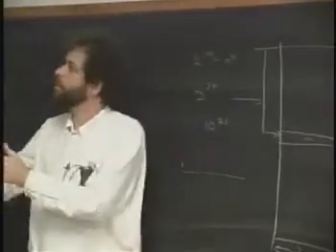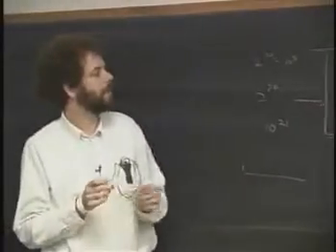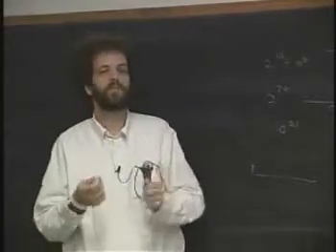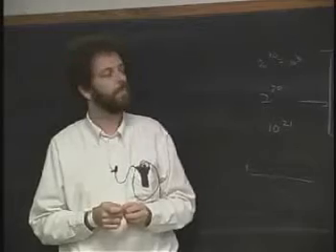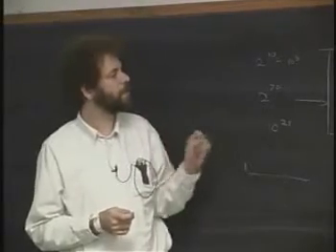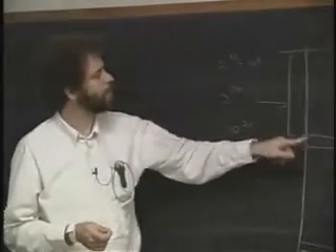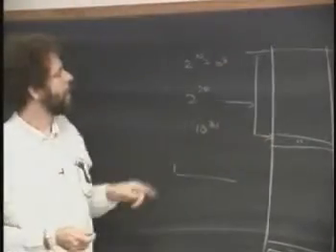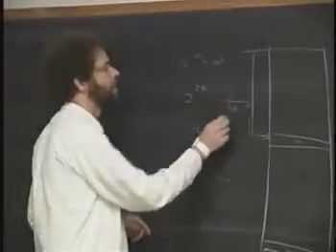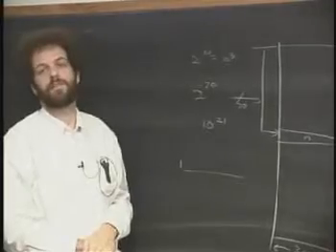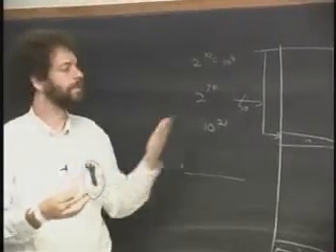So even though we could implement this thing as what's called a lookup table or a memory, notice the architecture here is simply that of a memory, it's impractical to do that, okay? But theoretically, at least, it is what's called a combinatoric logic function, which means that the output is purely a function of whatever the combination is of the 70 bits that go into figuring out how far down in the combination table we're going to look. It's just a pure map from in to out with 70 bits in and 32 bits out. So that's not good enough.